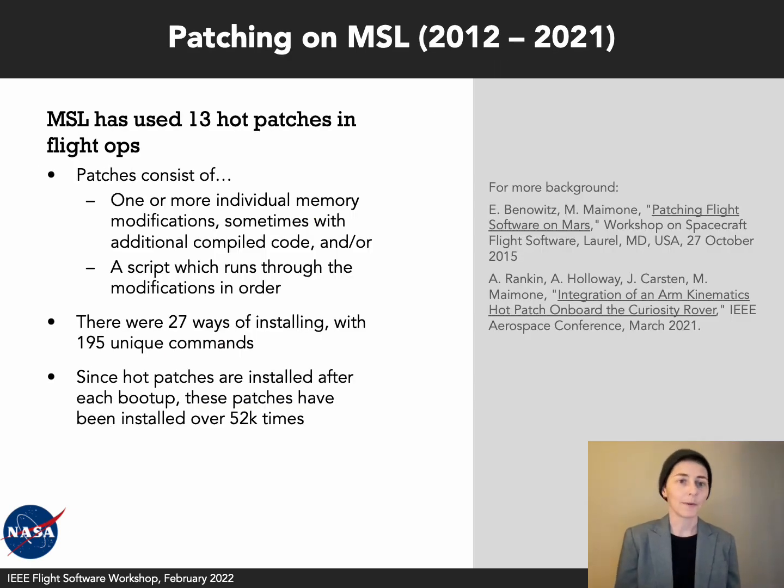On MSL, we have used 13 hot patches in flight operations, where a patch consists of one or more individual memory modifications, sometimes with additional compiled code, and sometimes also a script that runs through those modifications in order.